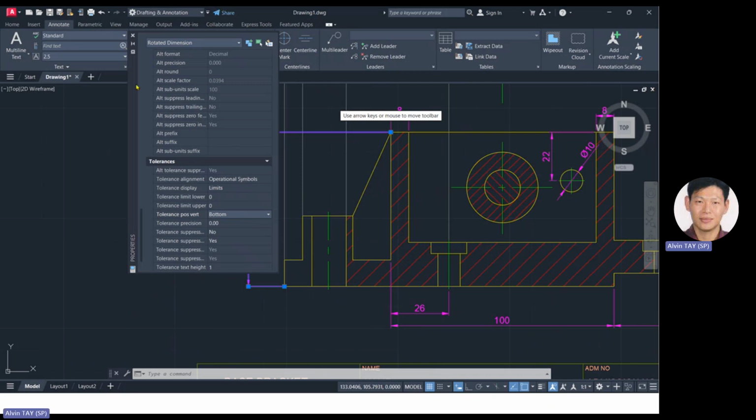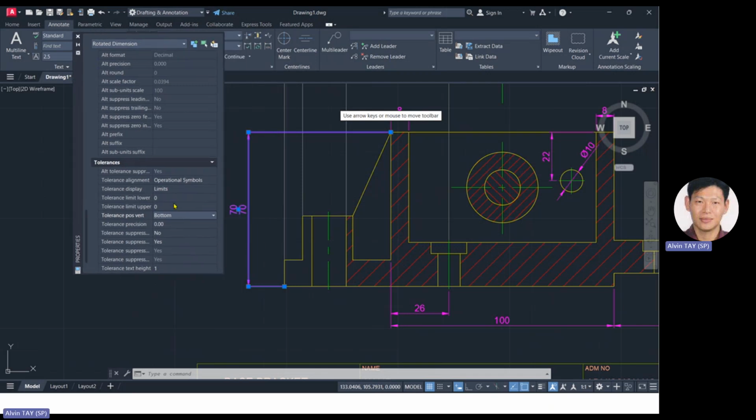Okay, never mind. Just click first. You notice, how come it's 70, 70? Then not correct. You know that it's going to be deviation. Global is positive 0.1. So if I were to key in 0.1, it will automatically be negative. So how to become a positive? Put a negative sign in front. Then your lower will become a positive. Upper no need, upper just put 0.2.